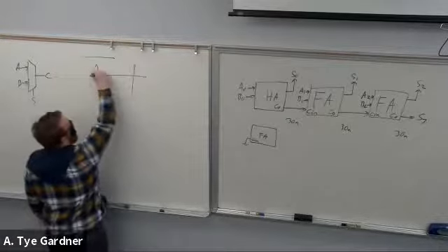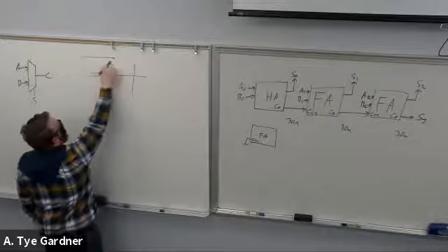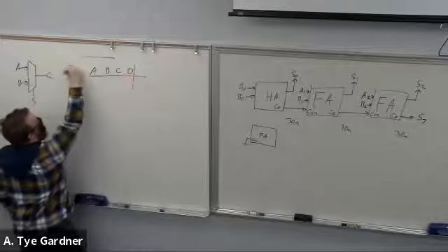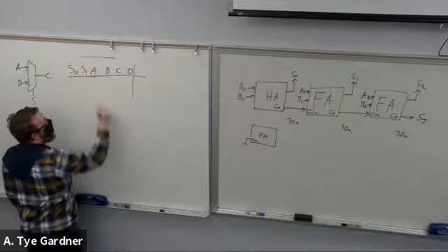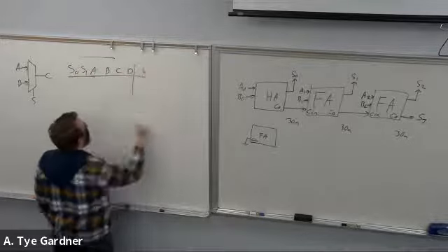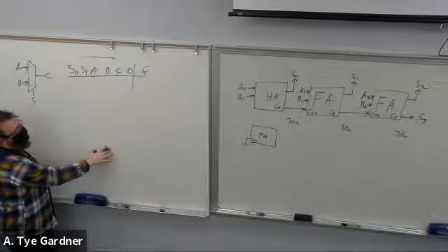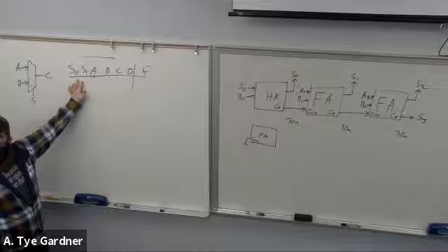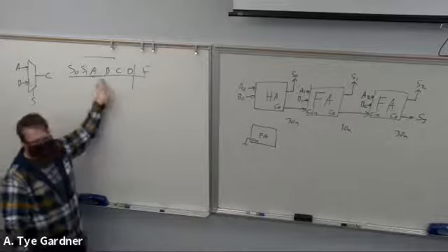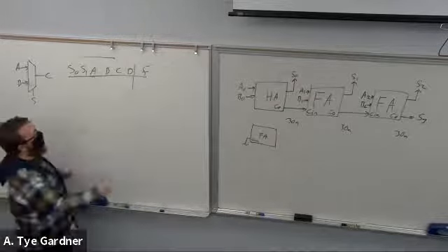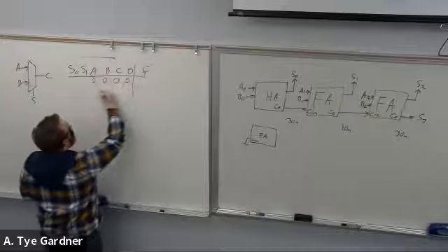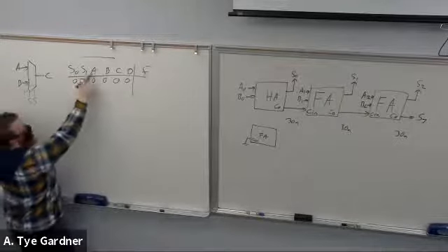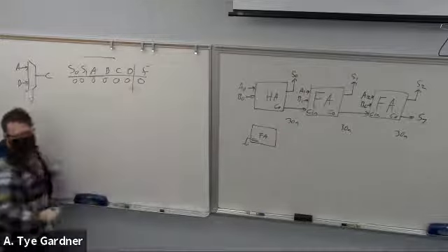I have inputs A, B, C, D, select 0, and select 1, and I output F. Depending on what select 0 and select 1 are, F is equal to A, B, C, or D. So if select is 0, 0, that means I want A, so F is 0.